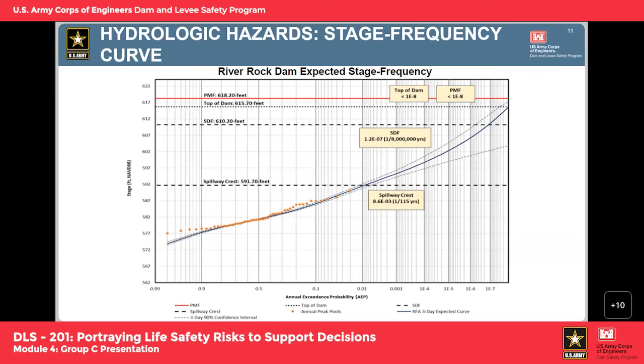I will point out, the plotting positions we use were from 1970 to 2018. So with some of these dams, when we have historic floods, we'll route them through the project to see what stages they would have created. So there are probably some opportunities to try to better understand some of those stage plotting positions if we did a little bit additional work. But specifically from that 0.9 AEP to more frequent, I do not have a great explanation for why the curve is not fitting those points. Okay, thanks.